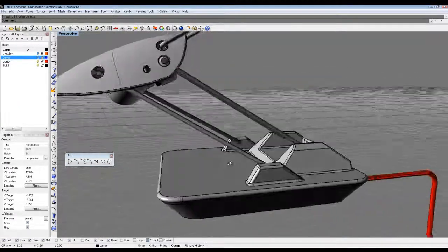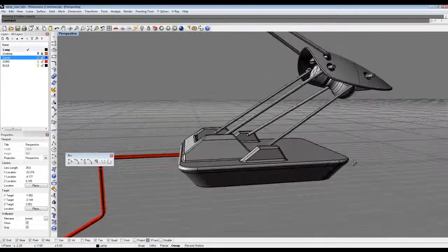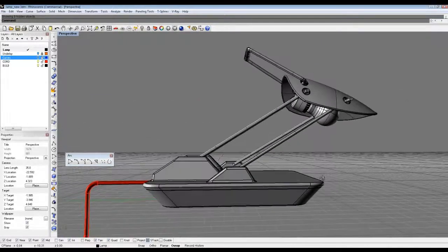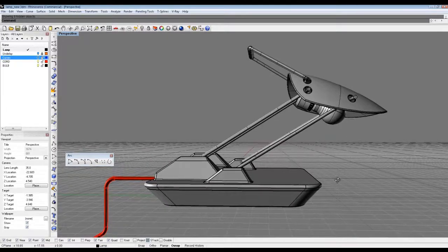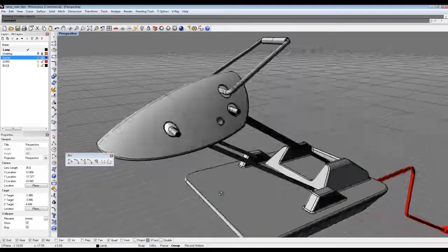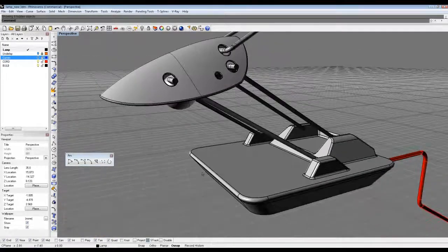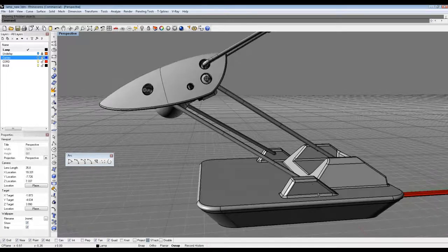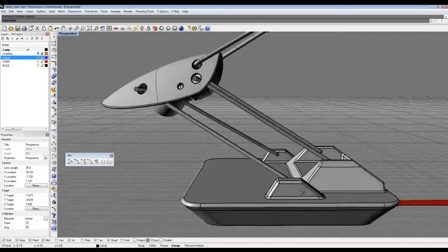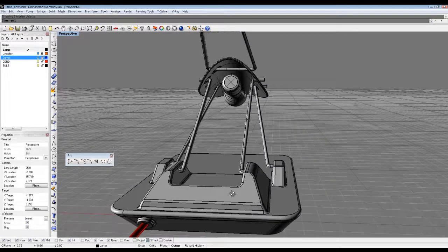So it really does offer you a nice balance between sketching out an idea and then going back and editing it, keeping in mind that sometimes, as you saw with the base, the fillets can be a little bit daunting at times, but it's just a matter of A, the size of the fillet that you're using, and B, just kind of how your mesh is drawn out.